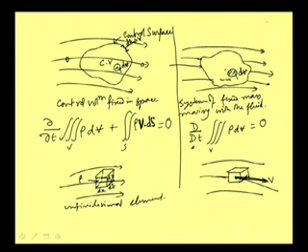Then the flow velocity u and rho u, and how much total volume is moving through this part, we can write as u, and the sectional area will be dz into dy, and then multiplied by rho we get what the flow is here. And then on the other side, when the flow velocity is u, per unit area the mass flowing is rho u.